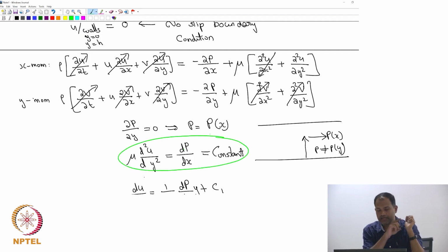Okay. It says that a pressure gradient generates a fluid flow, that is what I interpreted it as. Or you could say that yes, there is a flow that will generate a pressure gradient. The way we typically do it is we apply a force and get a motion. We do not say that we actually get a motion and because of that, that force existed, which is an equivalent description, but it is probably less physical than interpreting it the other way. So, flow will be typically associated with a pressure variation, or a pressure variation would generate a flow.